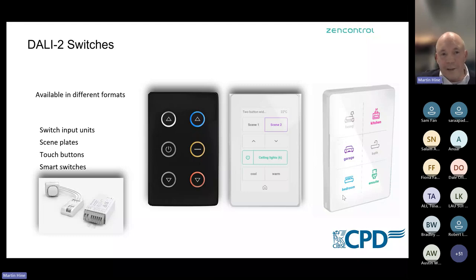You can also have intelligent touch panels that allow you to go between the lighting, the HVAC, the blind controls and AV. So over the communication, it's backwards compatible, bidirectional information through the DALI to the third-party systems through the application controller to the BMS via BACnet or MQTT to third-party products. You can create this bidirectional control over the DALI network to various types of switch interfaces.